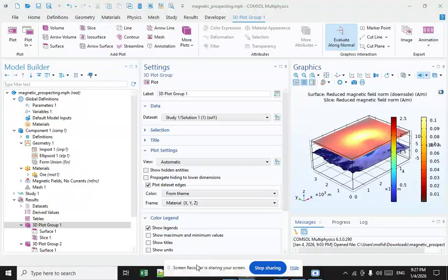And the methodology: airborne surveys are efficient for mapping large inaccessible areas using airplanes or helicopters. Ground surveys involve portable magnetometers for detailed high resolution mapping, and the next one is data interpretation, which involves reducing data to identify local anomalies, often using computerized models to specify the nature of the subsurface sources.